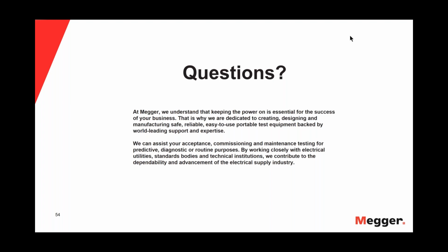If it will not blow up when you do the hipot test, and that's what the question implies, it doesn't blow up, it holds, you might be able to find that location if you would do this phase comparison method. You might. I'm saying be careful.